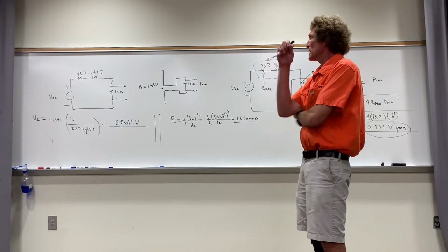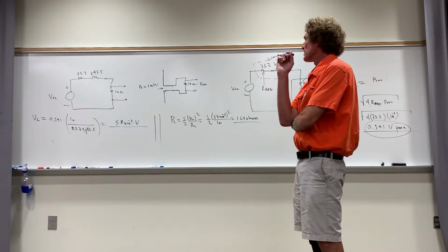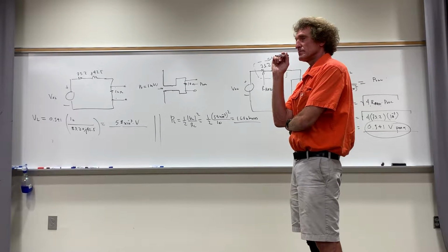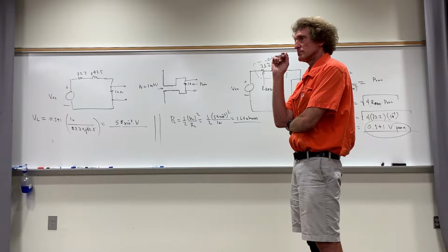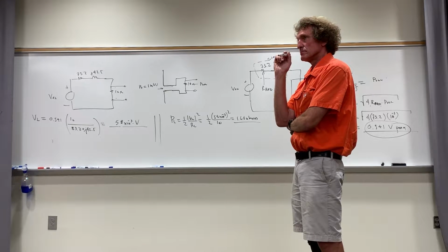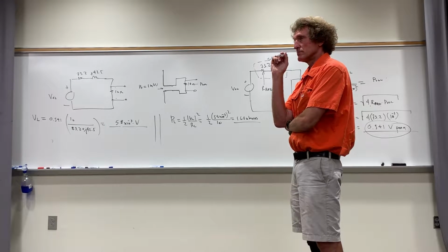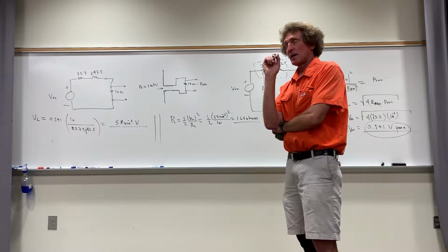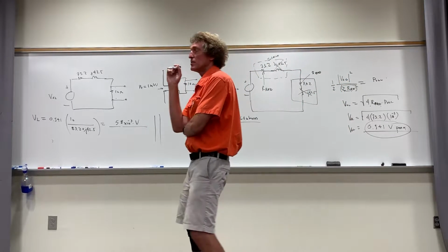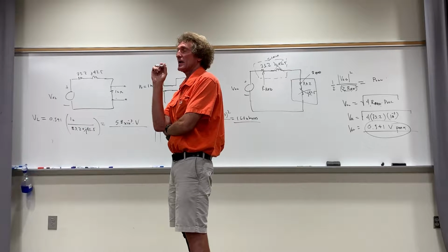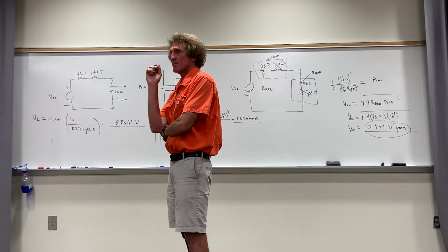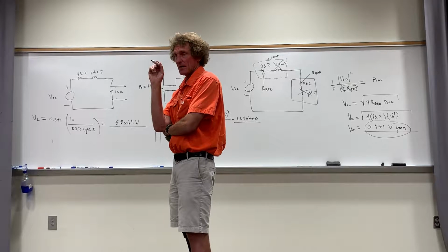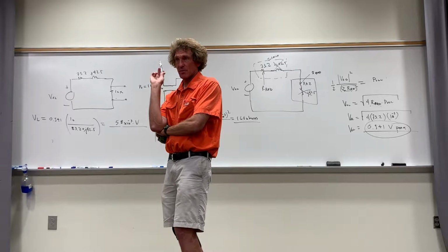Wait a second, does he say, read the problem again. Consider a lossless half-wave dipole antenna. If the antenna is delivering 1 milliwatt to a matched load, determine the received power if the load is changed to 10 plus j0 ohms. He could be saying it's not an exact half-wave dipole, it's cut down to 0.485 lambda. Remember, 0.485 lambda gets rid of the reactive component, do you all remember that?